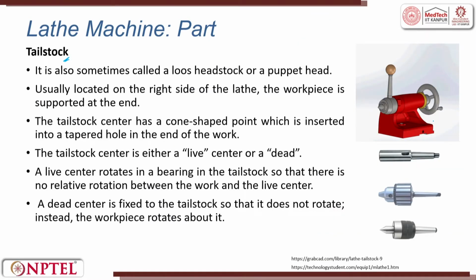Tailstock is the other end, which we already saw. There is a handle which rotates and then there is a rack. When you move, this tries to advance the tailstock, right? The tip. Okay. It is sometimes called a loose headstock or a puppet head, usually located on the right hand side. Left hand side is headstock, right hand side is the tailstock. The workpiece is supported at the end.